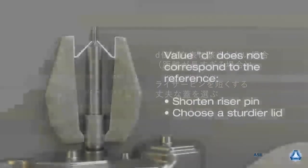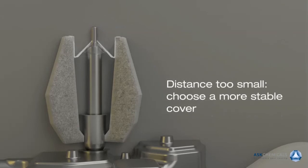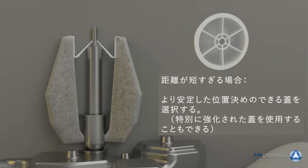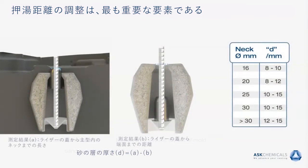If the distance is too large, the correct distance can be achieved by shortening the standard riser pins. A distance that is too small can be corrected by using risers with special reinforced covers. Correctly adjusted riser distances guarantee the perfect functioning of EXACTCAST OPTIMA risers.